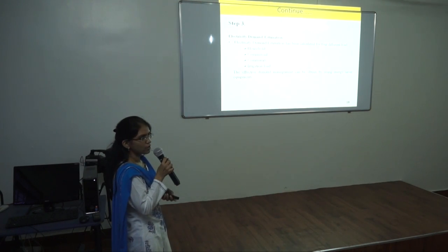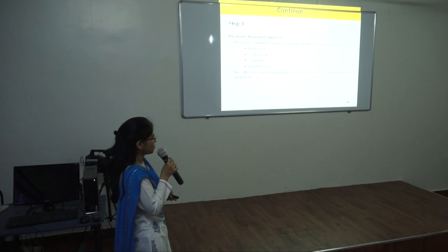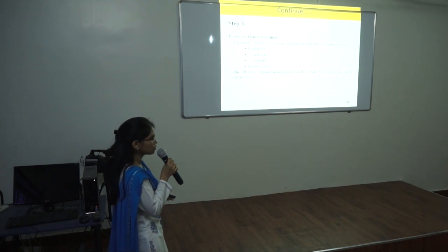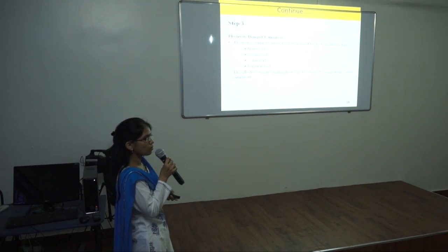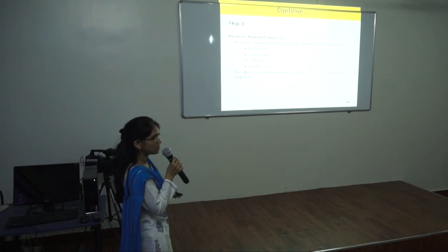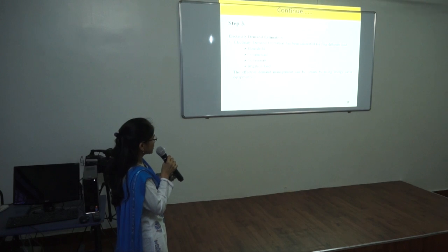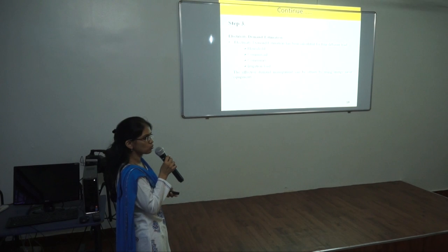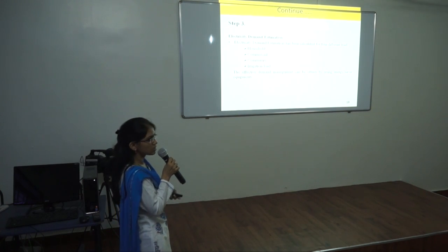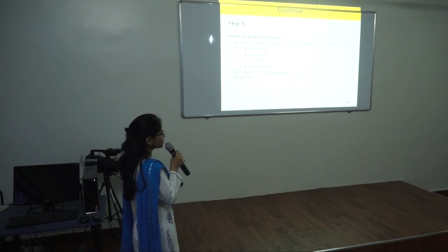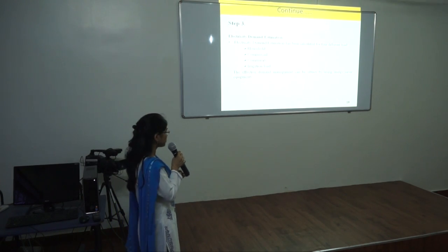In step number 3, we find out the electricity demand estimation. For determination of electricity demand, I have considered 4 different loads. First is the household load, which includes the load of lighting. Second is the commercial load, which includes the load of daily need shops and flour mill. Third is the community load, which includes the load of primary health centers, schools and street lights. And last is the irrigation load, which is used for water pumping for agricultural purposes. Effective demand management can be obtained by using energy saver equipment.